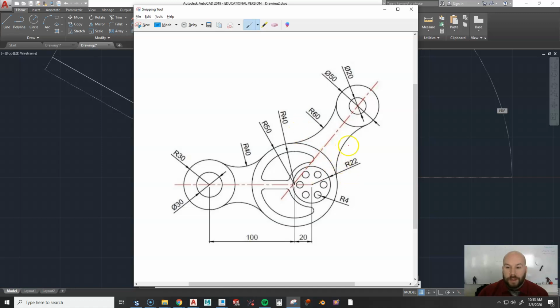And if I find that there's missing dimensions, I add them in. In this scenario, there are a lot of missing dimensions. For example, I don't have an angle here for what angle this is at. I can assume it's 45 degrees because it kind of looks like that, but anyone who properly runs CAD understands you're not supposed to assume anything. Okay, if a machinist assumes that something's at 45 degrees and I just forgot to put a dimension of 50 degrees in there, well, now all of a sudden my part doesn't work and I wasted tons of money making this thing.